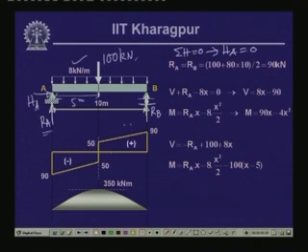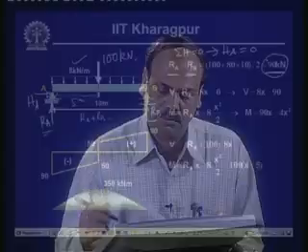So, for the reactive values RA and RB, RA plus RB equals the vertical force 100 plus 80 times 10, and then if we take the moment of all the forces with respect to A, we can evaluate the value of RB, and you will find that RA and RB will be equal to 90 kilonewton, which is half of the total load being carried by the beam, because RA and RB are symmetrically supporting the whole beam and the load is also symmetrical. So, the reactive values of RA and RB are the same, and the magnitude is equal to 90 kilonewton.